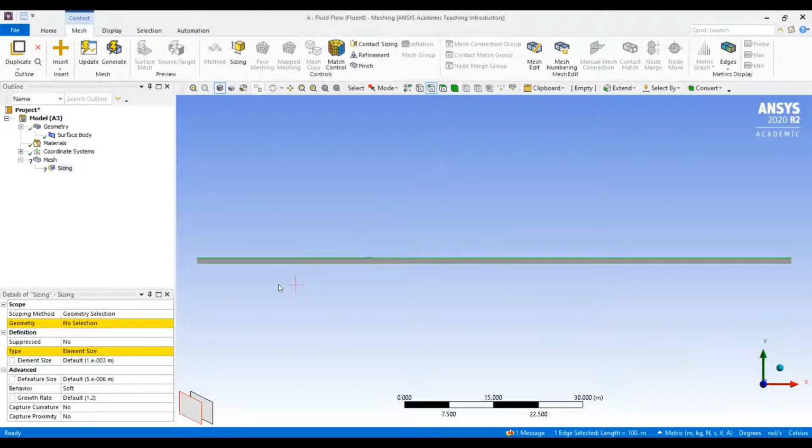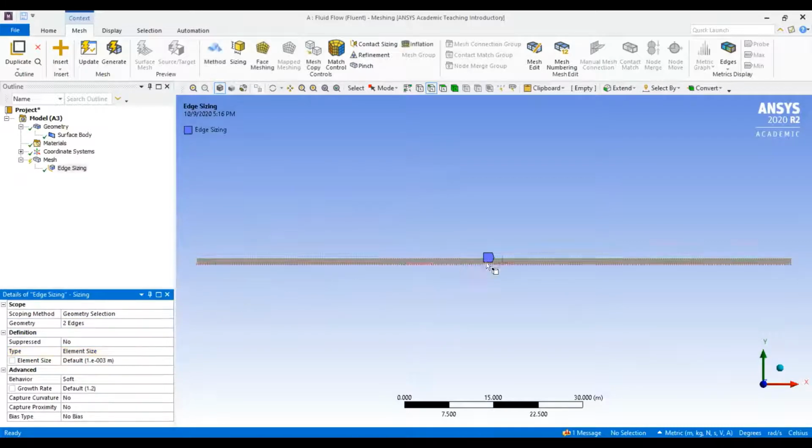So to do these two simultaneously, you hold down Control, and then you click on the other surface that you want to select. So you see that the top and the bottom side are green because I want them to have the same exact parameters without having to do this twice. So one more time, you hold down Control and you can select all the surfaces that you want to select at once. So what this is for, you're going to select for the geometry, apply. So now it knows, okay, I'm going to look at the sizing for the top and the bottom edges.